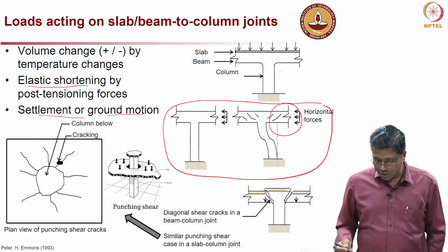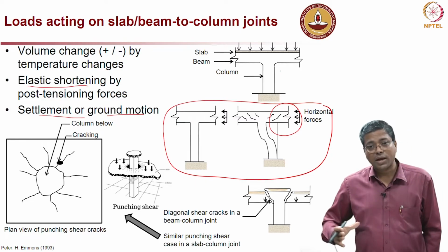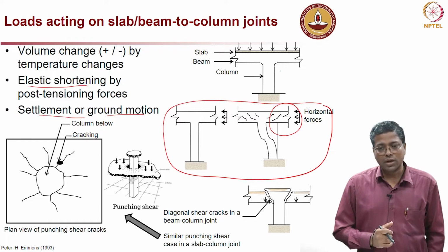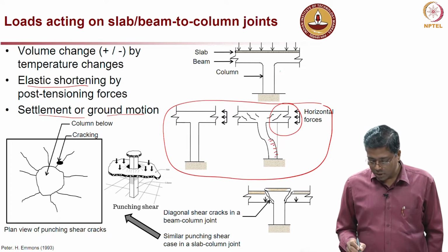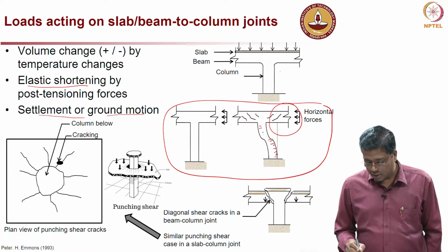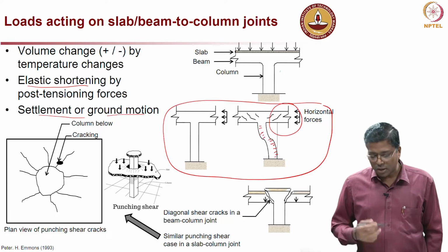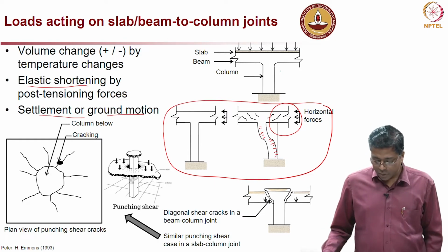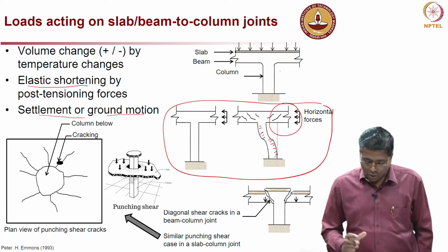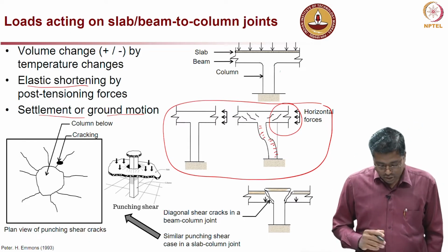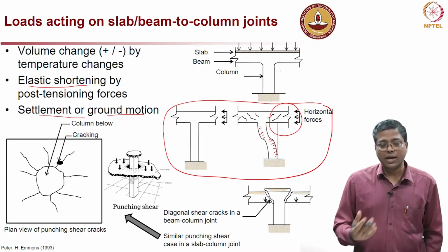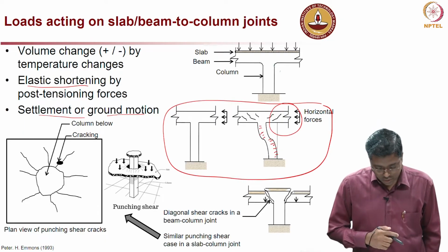That can eventually lead to some cracking on this portion of the column, and maybe also here, depending on the stress levels. You can see on which side of the column the cracks are and where they are. So, these all can help us in identifying the root cause.